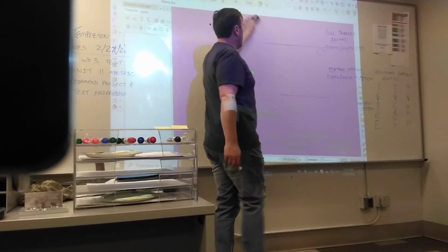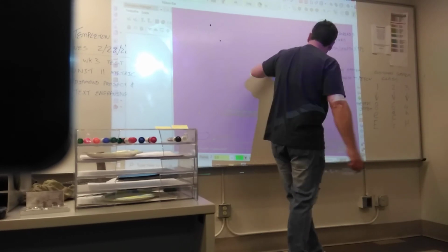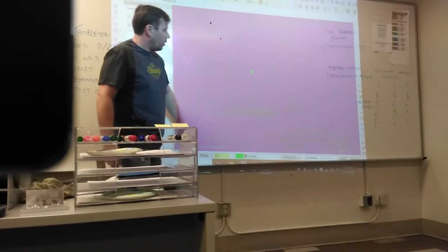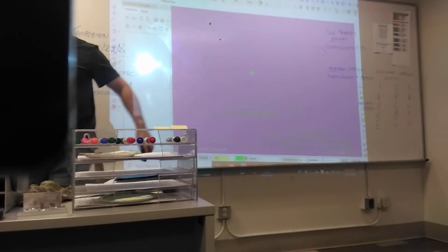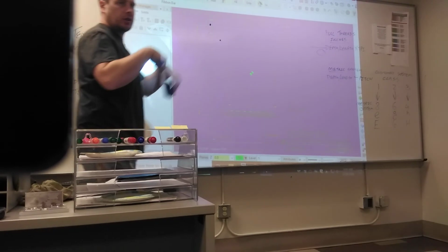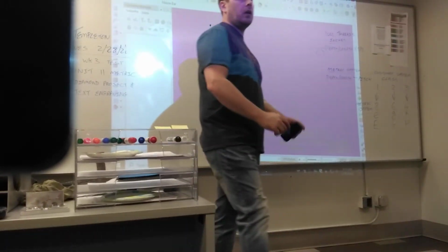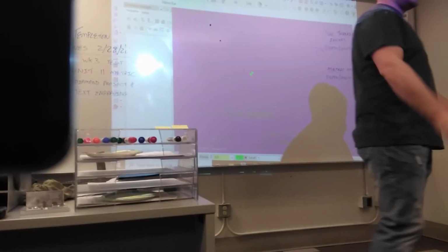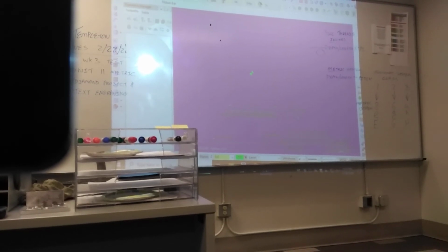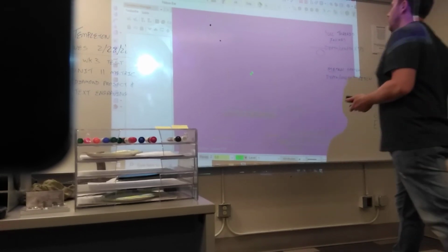This is very similar to the one you did as a pen plot, except this one we are going to machine. We're going to take that 3-inch by 3-inch piece that we cut the side the other day, and we're going to machine this engraving on the top of it. To do that, we're going to use a 1/8 ball end mill.